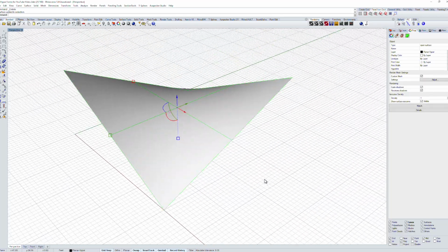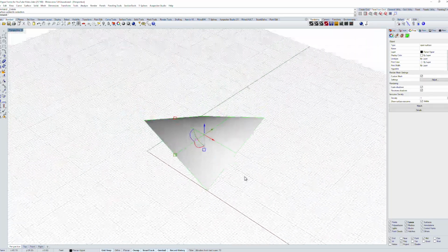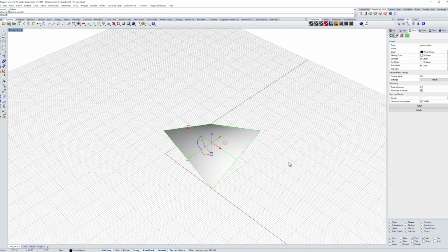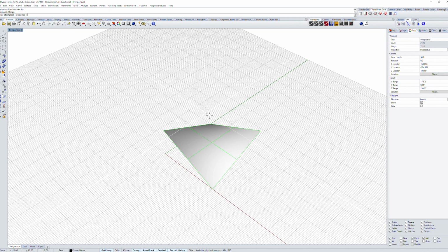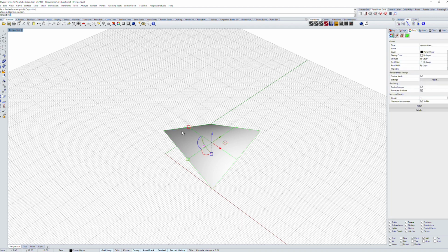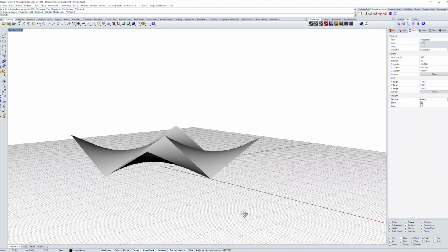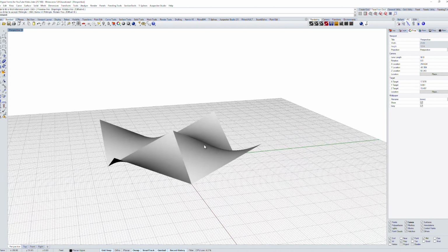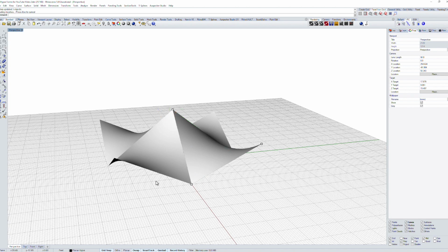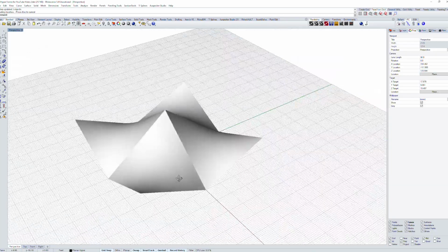So what can I do with a hyper like this? Well, let's play around with it. How about if we take this and rotate it about a center point? Let's make it a polar array, rather. And I'm going to make 4 copies and 360 degrees. And we get a structure like this. Now I think, because I have history turned on, if I change one of these, yes, they all change. That's the beautiful thing about history. So learn about record history. So we've got a structure.